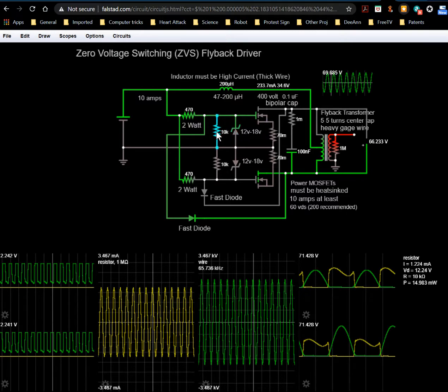That's why they have this regulator here, just so it doesn't fry the thing. Then they have this 10K resistor here, which acts like a voltage divider. So these two diodes, like this one and this one, I really wish you would have drawn this up here. It makes this diode less confusing, because it's associated with this transistor. So it would be nice if this were up here, but I could redraw it, but I mean, forget it.